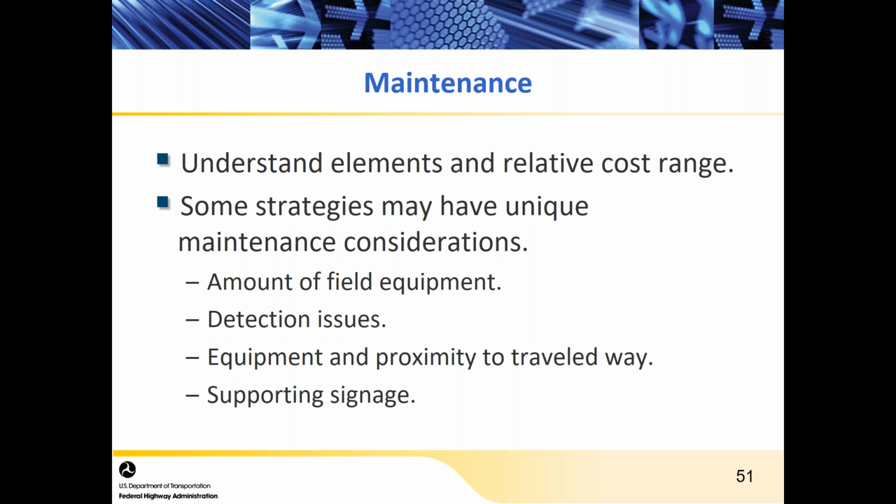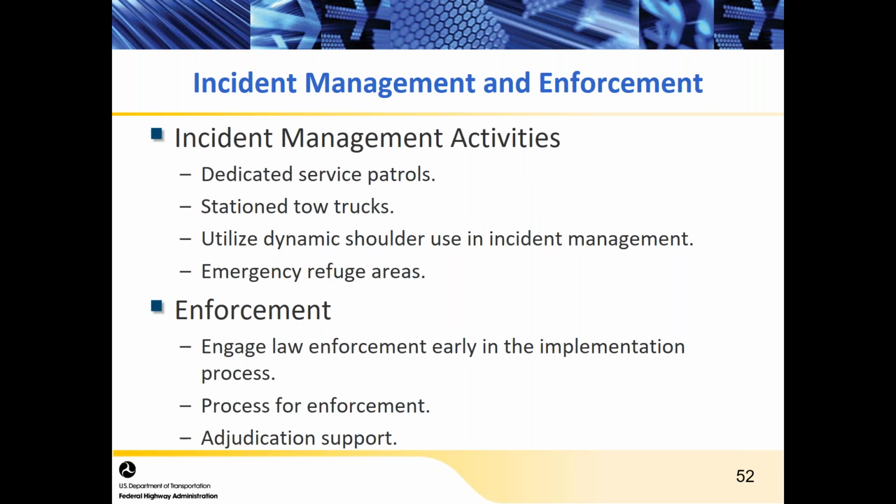Maintenance is very critical to the success of these strategies, as with all strategies that are driven by ITS technologies. You need to understand what the components of your system are, your field equipment, your equipment in the TMC, your detection, supporting signage. All of those elements are very important to understand what the cost range is. Is a strategy a moderate cost versus a very expensive cost, depending on how you're going to deploy it, and how often you might need to replace field equipment, having redundant systems, having backup equipment. What happens when the manufacturer of your particular piece of equipment goes out of business? Then what do you do if you have a legacy system and you can't afford to replace it immediately? Do you stockpile replacement parts to get you through until such time that it starts to fail, and then you want to replace it as part of your ongoing maintenance? So there's a lot of issues to consider there in maintenance.